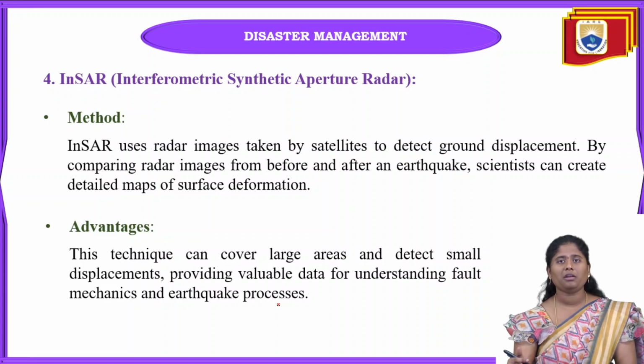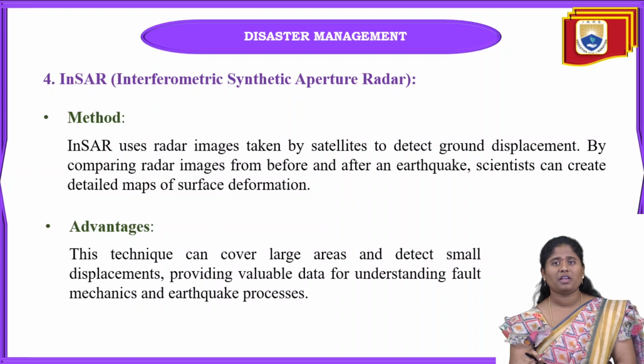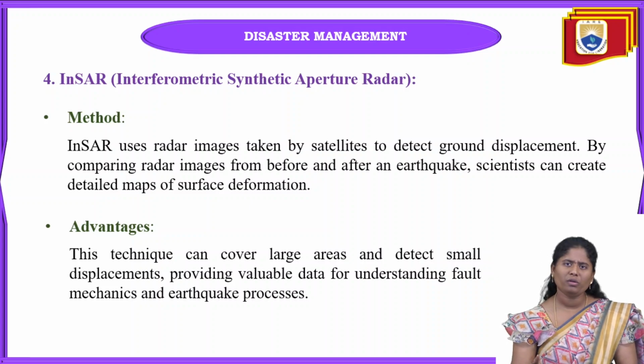And what is the main advantage of this InSAR? It can cover large areas, and it can detect very small displacements, even at the micro level. Because of this InSAR data, they are able to provide understanding of fault mechanisms and also earthquake processes. Of course, InSAR data and GPS data both come from the satellite itself.